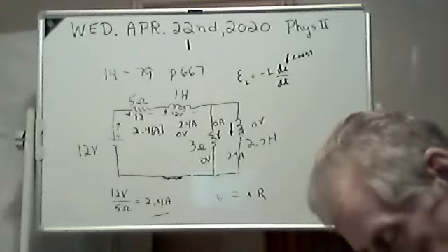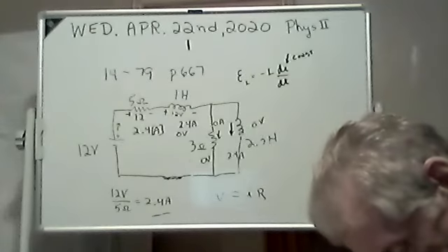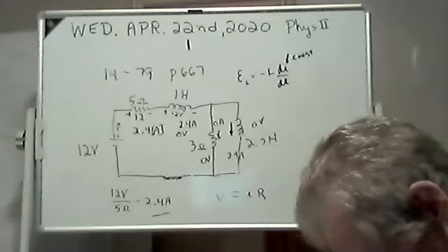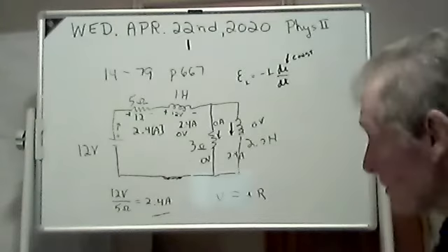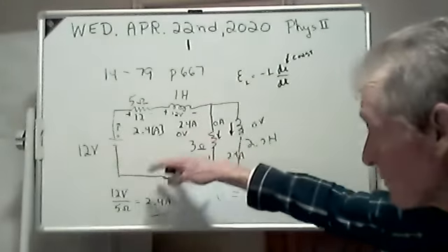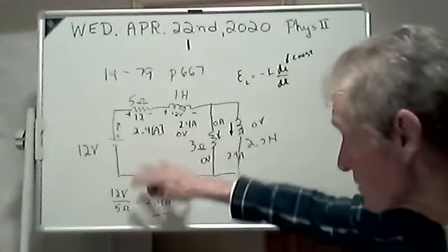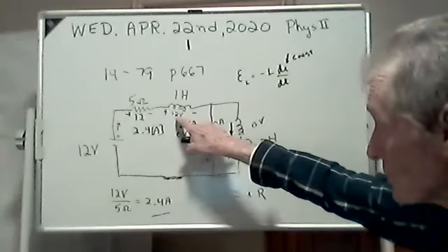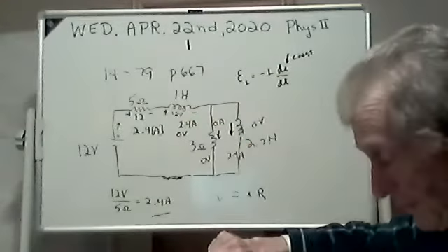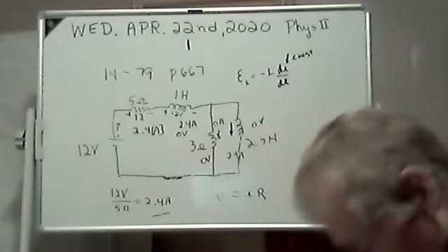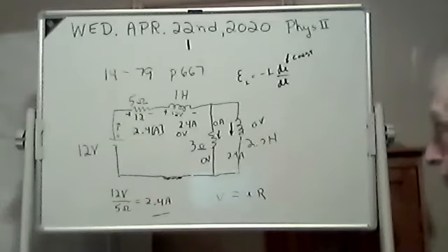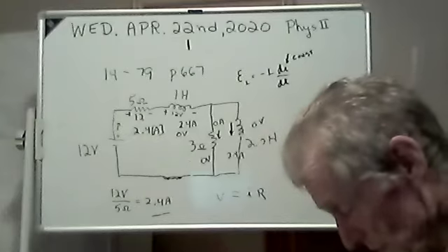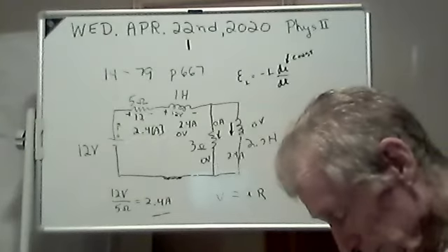And I'll give you a pretend quiz here in a minute. Let's see, 1479. They said 0 amps to start with. Remember, I erased it, but when you first threw the switch, you had 0 amps. However, you did have voltage on the inductor. And then they said 2.4 amps after the thing reaches steady state. So we got the right answers, and I'm pretty happy about it.